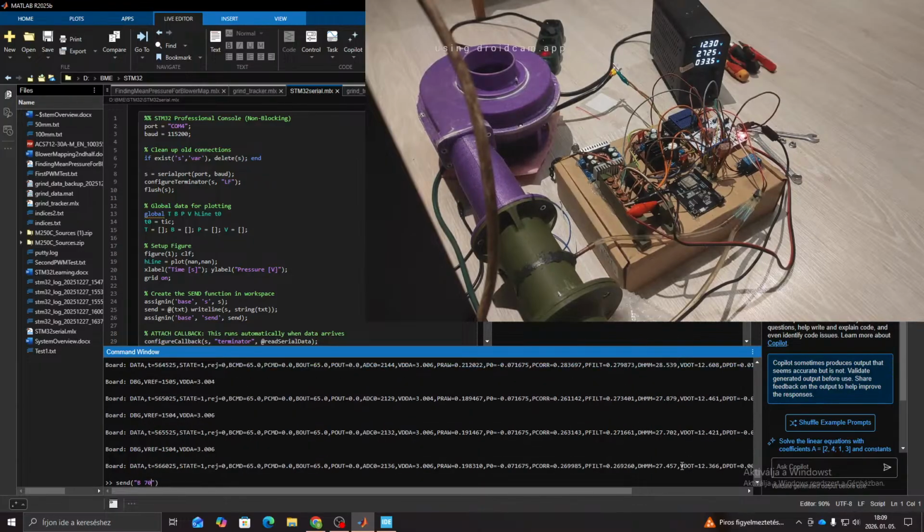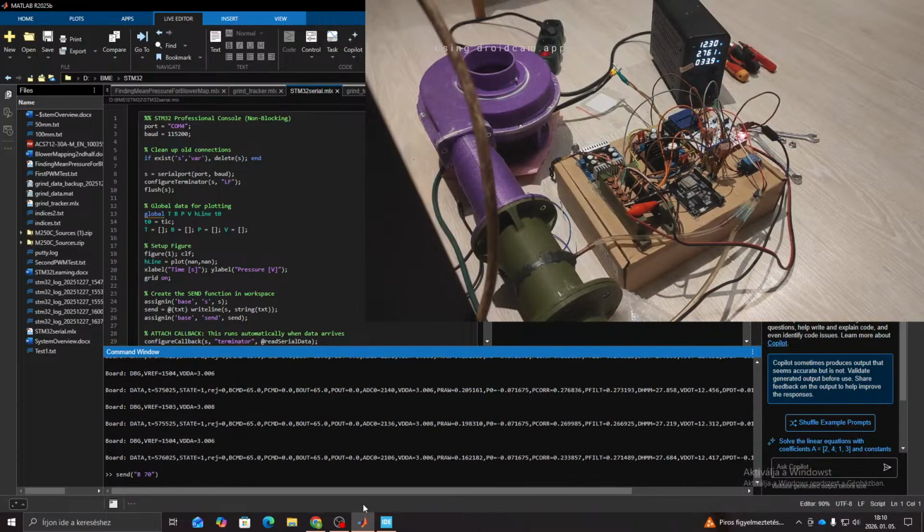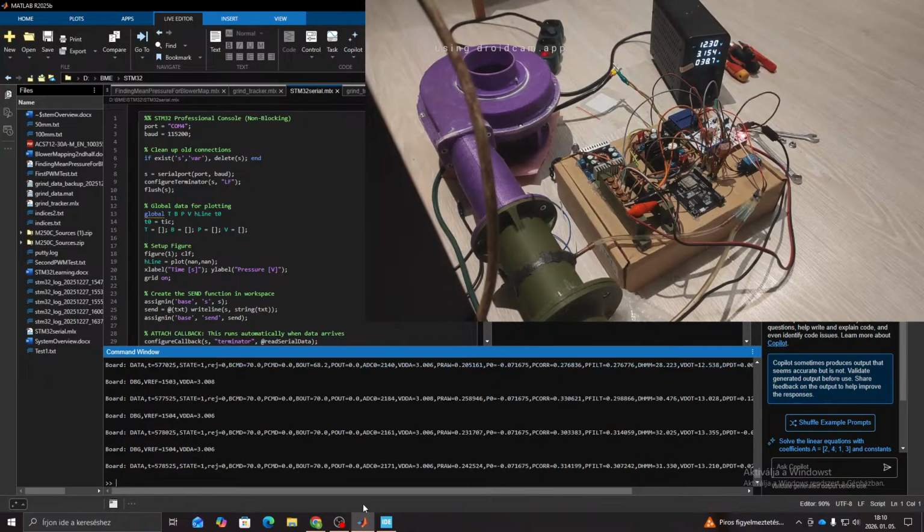This is liters per second. So this is 12.3 liters per second roughly that we are pumping now. We set the guide up to 70% because I think we have been fine with that. 38 watts ish of power drawn, pretty stable, around 1.2 watts of variance.